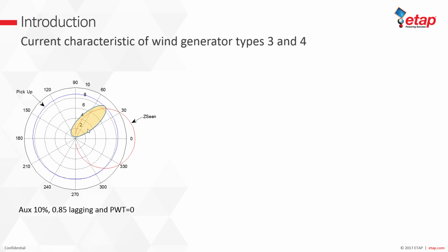While there is no fault on the system and there is no generation, it's just reactive power support of the wind turbine generators. Now on the capacitive side, as you see, we enter the fourth quadrant when the angle is more than 40-50 degrees.